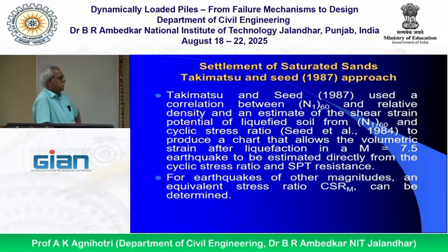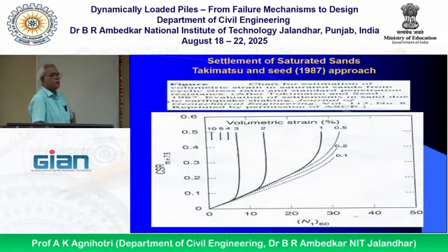These curves have been provided. We will perform SPT as earlier. From SPT data N160 you have. Corresponding to N160, you can calculate CSR M7.5, CSR M7.5 and N160, and corresponding to that, wherever your point falls, you can calculate volumetric strain. Clear?